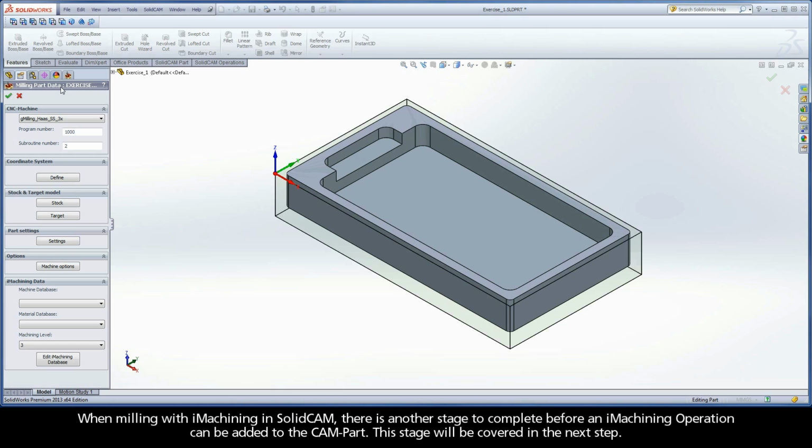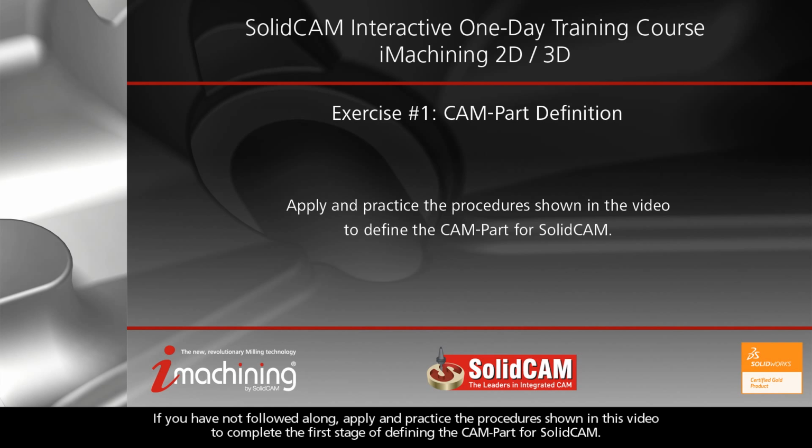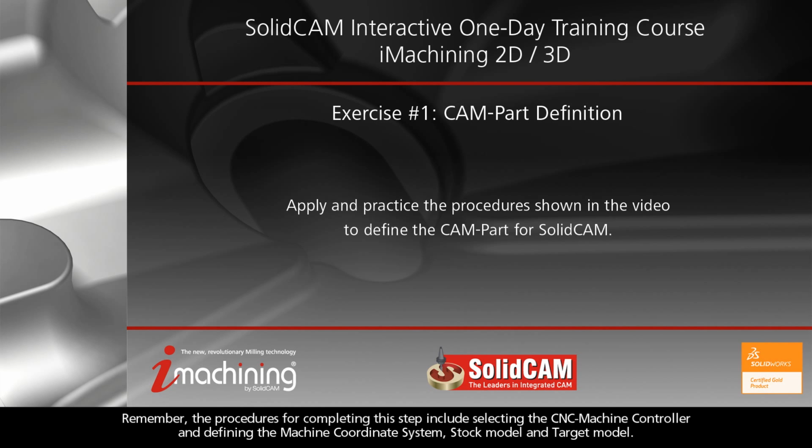When milling with iMachining in SolidCAM, there is another stage to complete before an iMachining operation can be added to the CAM part. This stage will be covered in the next step. If you have not followed along, apply and practice the procedures shown in this video to complete the first stage of defining the CAM part for SolidCAM. Remember, the procedures for completing this step include selecting the CNC machine controller and defining the machine coordinate system, stock model, and target model.